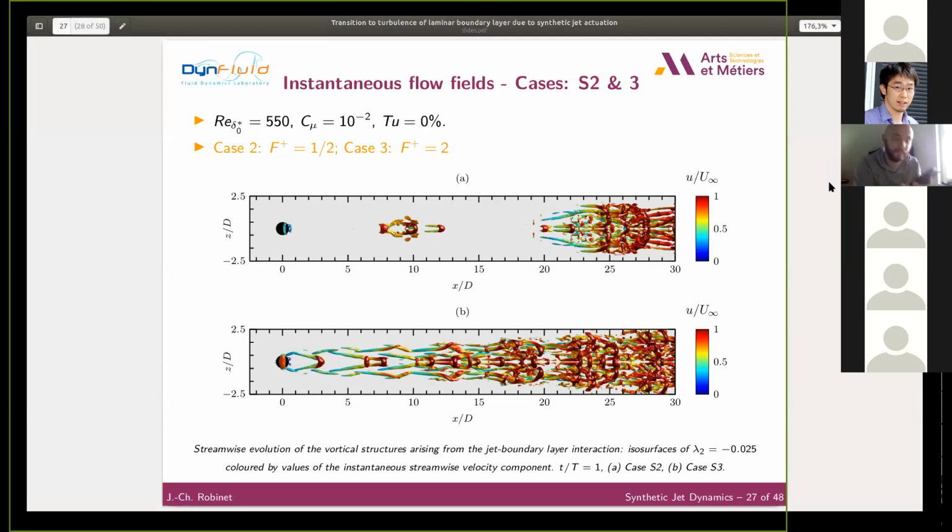Perhaps, but in this case, it's necessary to have a stochastic forcing to break the symmetry. Because if you compute in a larger domain, the symmetry remains in the far field. In all cases computed here, it's like this, even if the behavior of the flow seems to be very complex. In fact, it's always symmetric. And it's necessary to inject a small scale in the spanwise direction to have energy transfer between the different scales and to start the real turbulence behavior. Okay, thank you.